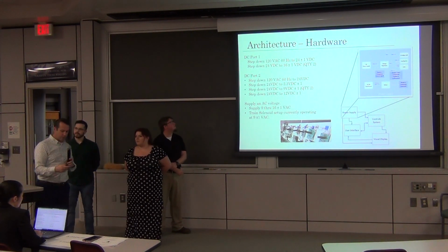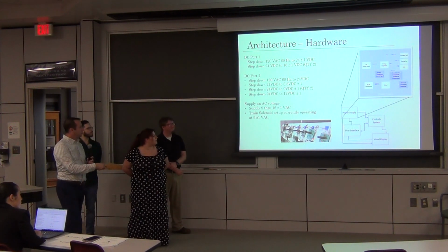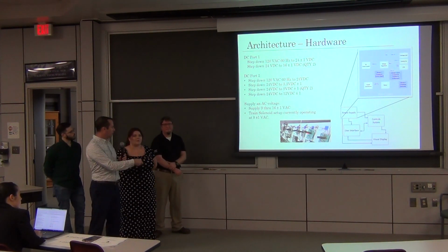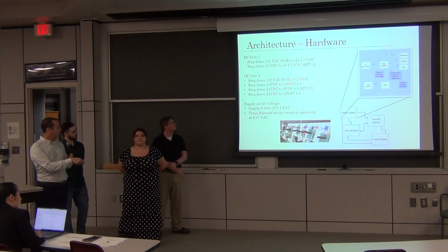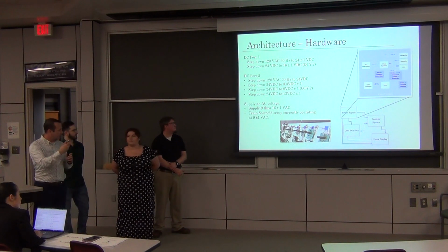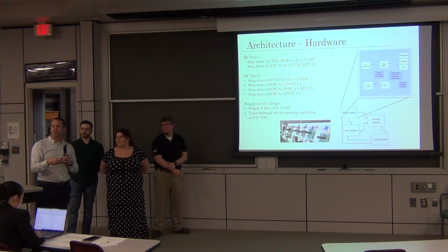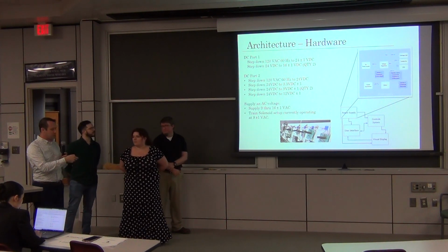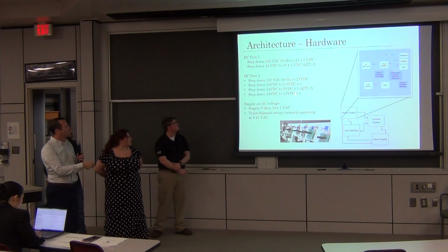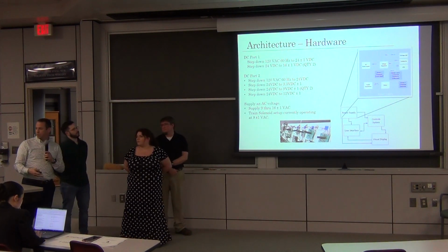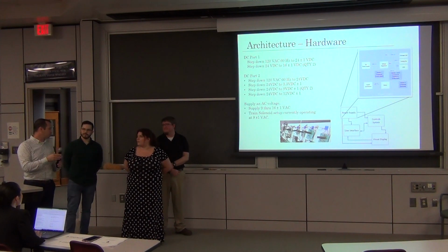As you can see, we had to put quite a bit of regulators to step them down using LM317 microchips. That works off the proportional difference of the resistors that are on the outside of the chip feeding in, and then that steps down the voltage to the proper levels. Levels we needed, more specifically, were 3.3, 9, and 12 volts. All of those then were sent downstream, which I'm pretty sure everyone saw in our walk around. Everything was working.